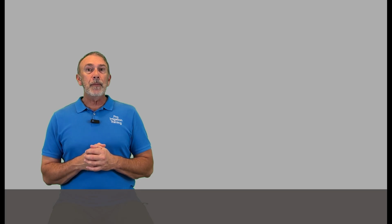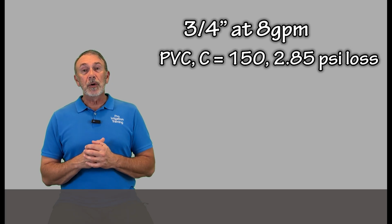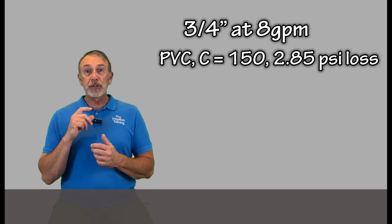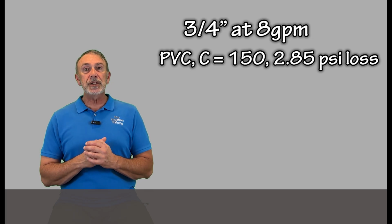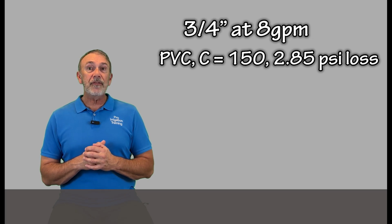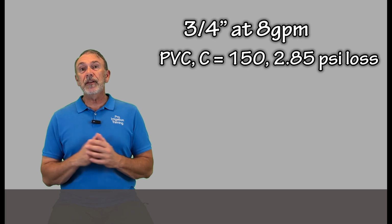We're going to take the example of a 3/4 inch size of pipe at 8 gallons per minute of flow. So let's first look at PVC, which has a C factor of 150, and it's going to be the smoothest of these types of pipes that we talk about, and it has a friction loss of 2.85 psi of loss per 100 feet of pipe.